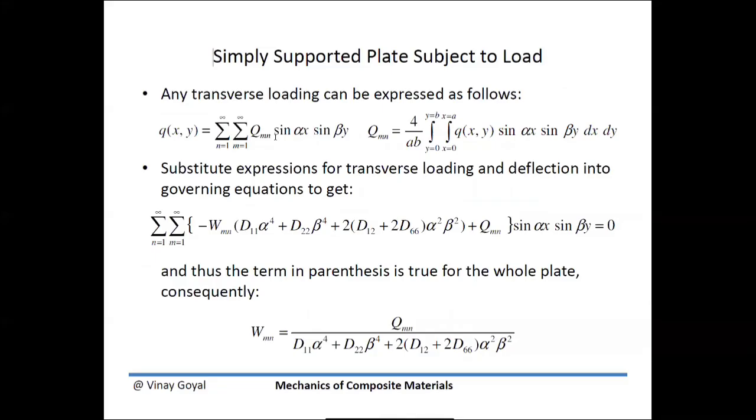If you look at a more advanced math book, QMN can be given by that. So if I have a distributed load Q of some kind, it could be uniform, whatever it is. If it's uniform, then this is a very easy integral. Whatever it is, this distributed load can be represented in this manner, and QMN looks like this. For uniform load, you will put, let's say, 1 psi there and integrate this.